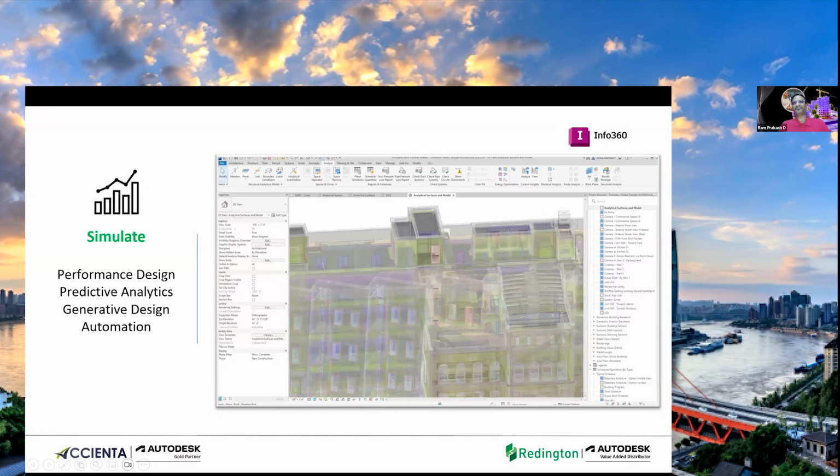So yeah, now the other important thing here is embodied carbon emission. We have a lot of energy analysis coming up here. Probably architects need to have the building with the sun and shadow settings. The mechanical engineer will have the building with the proper analysis of heating and cooling load calculations. And there's an application called Insight 360, which will help you get generated reports of embodied carbon emission, which is also an important one when it comes to your AEC projects, I mean architecture, engineering, and construction operation projects over here. Yeah, next slide, Tali.